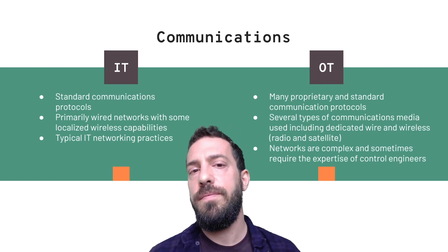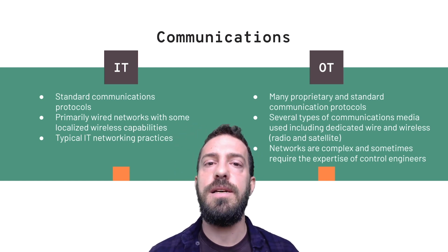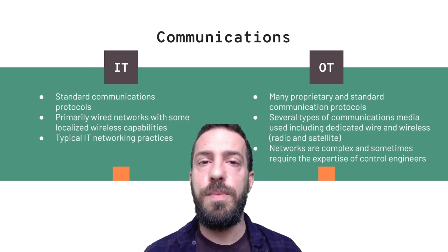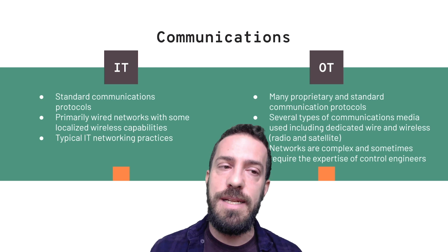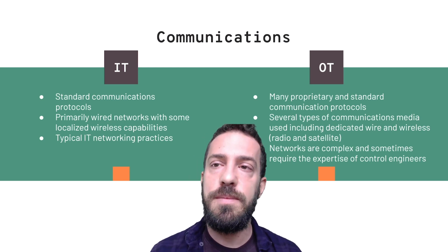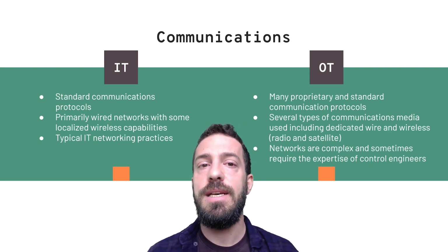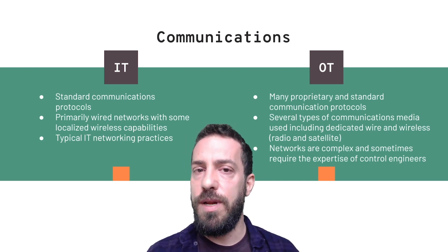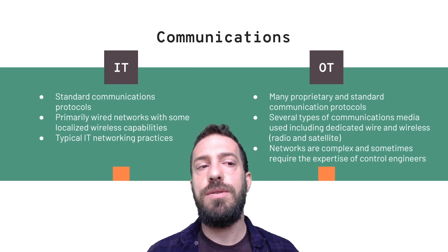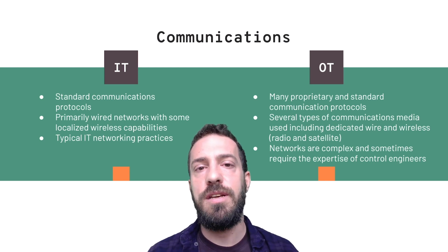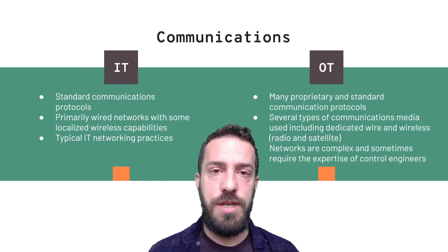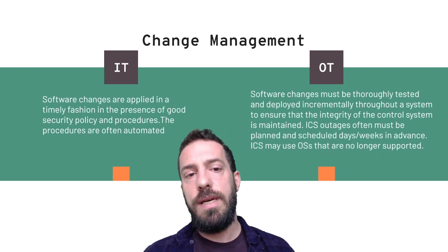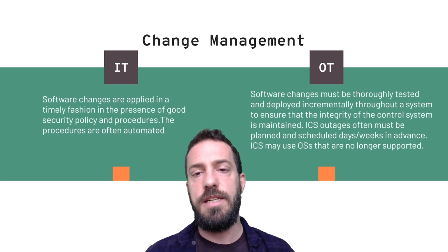You have to discuss with the control engineers, because you may be adding delays in the communication link, you're adding redundancy, you're resending messages for integrity, you're adding checksums, you're adding certificates. This adds delay. Is it supported? So you have to be in constant communication with your control engineer to ensure the appropriate methodology for securing communications in the OT systems. The next item to discuss is how change is managed, change management.